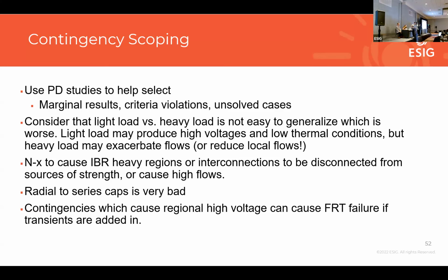And also in your light load case, if you're pushing your IBRs to your maximum power limit, you're probably going to have to turn down or maybe even shut off some of your synchronous machines in your study area, which is going to lower the strength of the network even more.